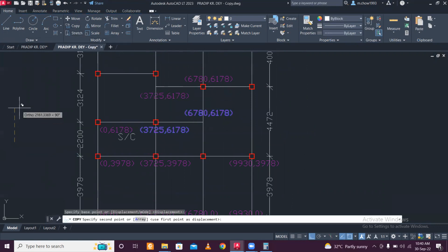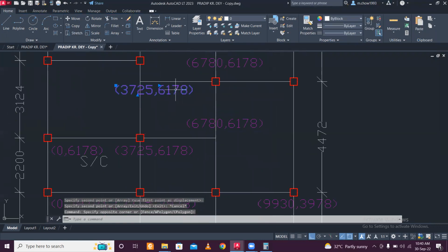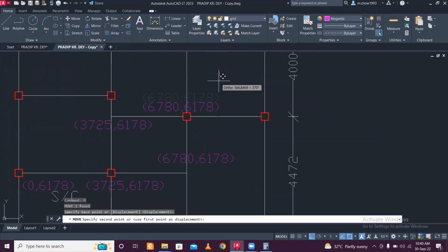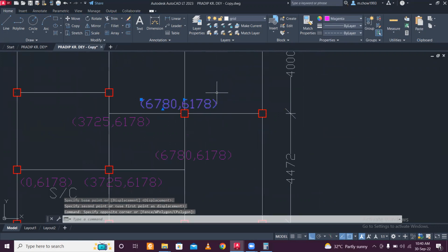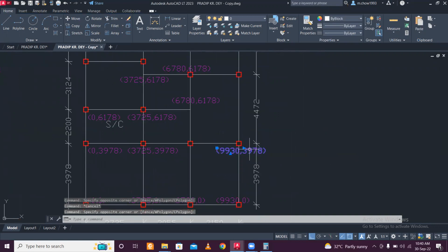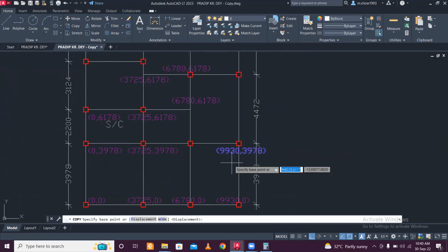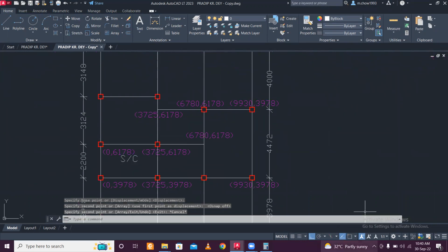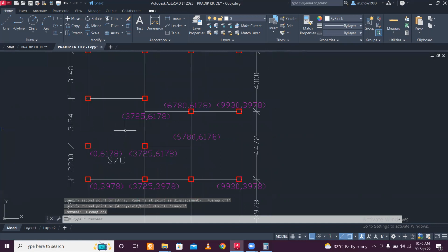Copy this for the next two levels. Here I might change the arrangement a little bit so that it makes space. Okay, now for the last one, the x coordinate as usual remains the same, only the y coordinate will differ. For the ease of pasting, let me turn off OSnap, then I can put it anywhere and then turn OSnap back on. Right.